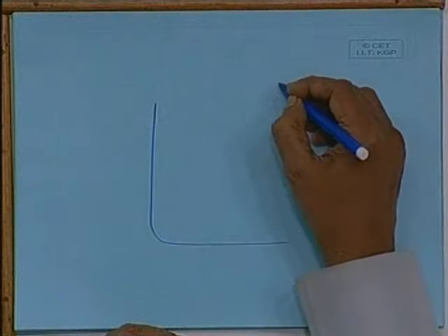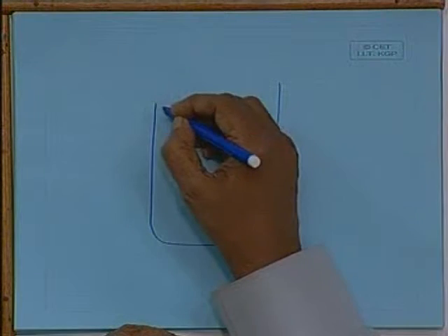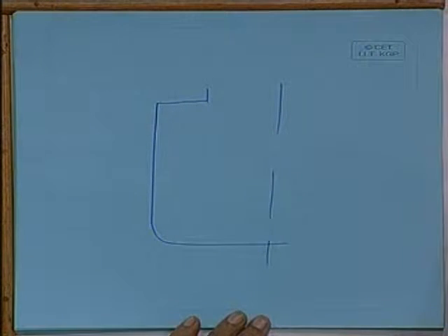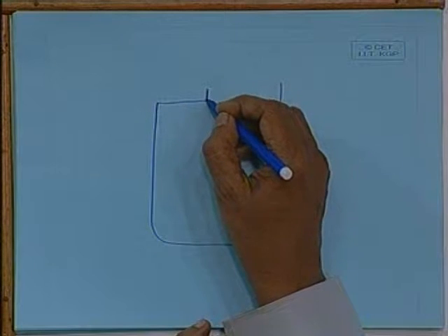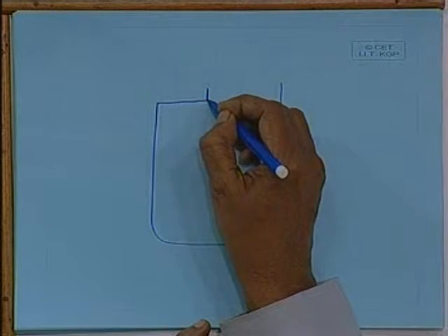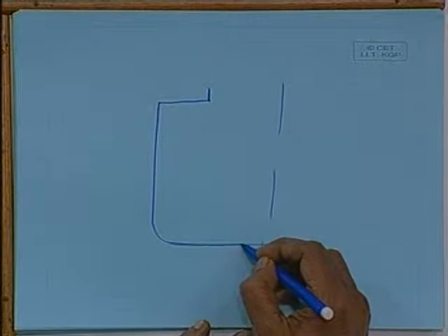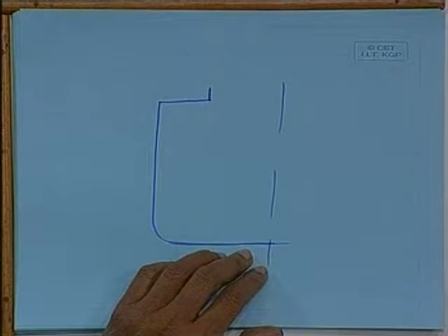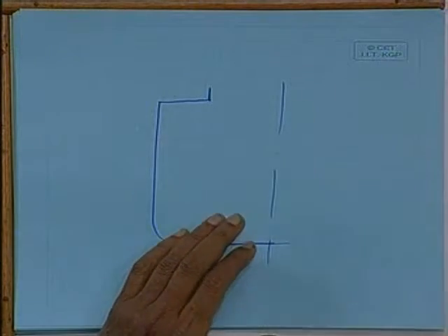I have a ship section here. I have calculated the section modulus, and you can assume that the deck plating and the keel plating have reduced by 25% thickness at the end of a 5-year cycle.